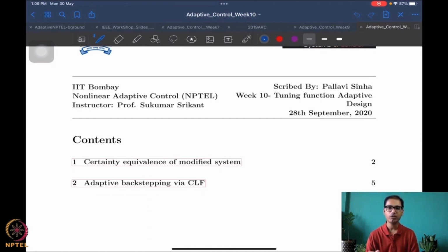We already improved on one design flaw in the adaptive integrator backstepping, which was that you have to create two parameter estimates per parameter. We were of course left with one issue in the extended matching, which is that the derivatives of the parameter update law appear in the control law.